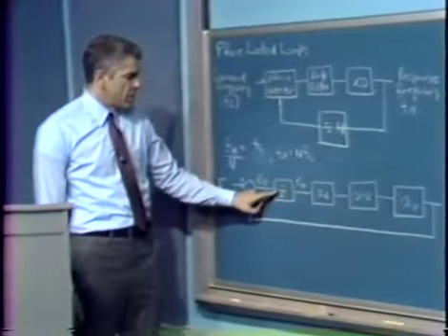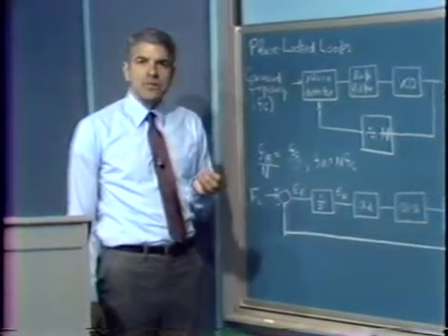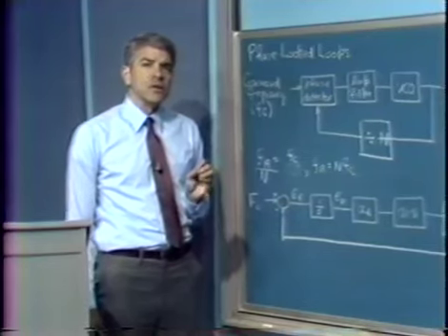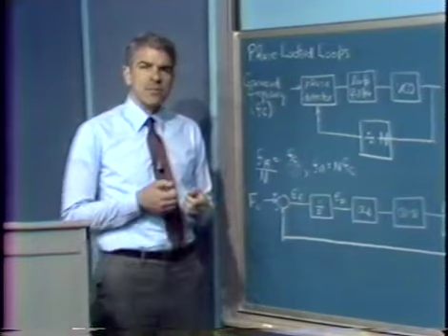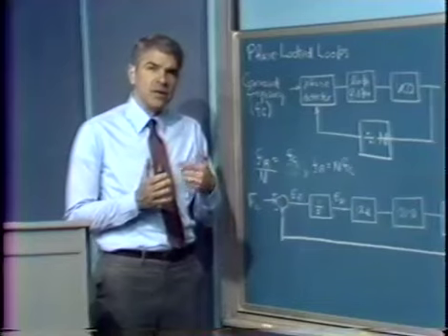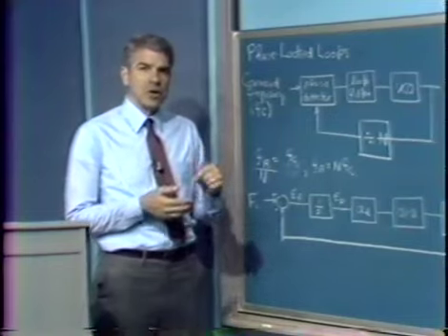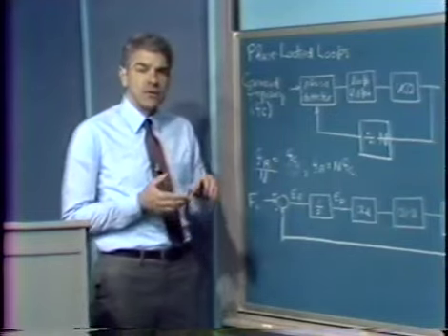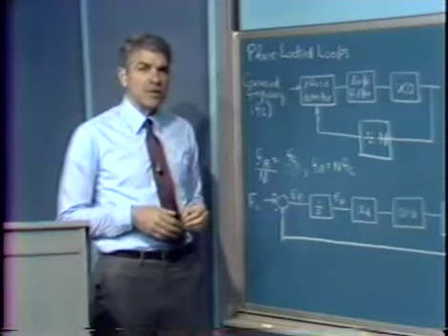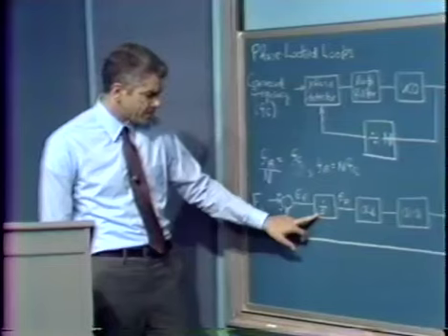The important thing here is that there's an intrinsic integration in this system that simply has to do with the conversion from frequency to phase. We've seen that sort of thing before in other systems. When we looked at mechanical systems that included a motor, we remember that when we put a fixed voltage onto a motor, we get an output angle that's a progressive function of time. If we have a fixed voltage on a motor, we get a ramp for the total output angle. And so if we write the transfer function that relates input voltage to output position, or theta, we get an integration in that transfer function. Here we have the same sort of thing, a physical process that gives us an integration.